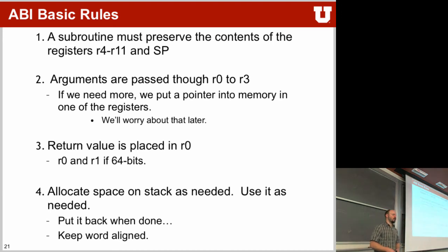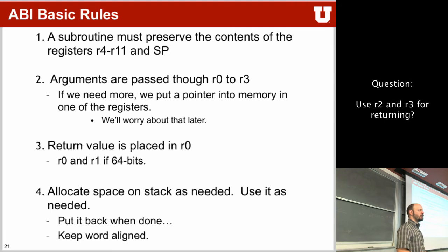You can use the stack as much as you want, but make sure that by the end, when you're done, it's back where it has been. Question? But you can't use R0 through R3 to return values, or is that used for the stack? I don't think you usually do. It's not in the ABI at least. So if it's more than 64-bit, you probably push it on the stack, or pass it through a memory location.